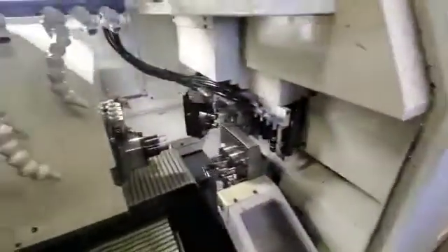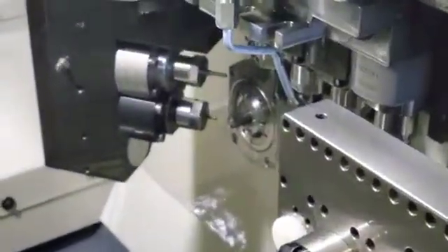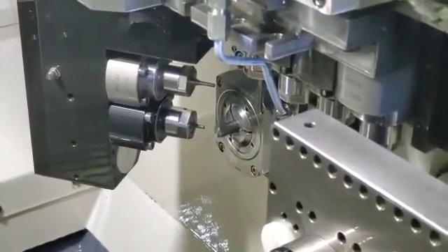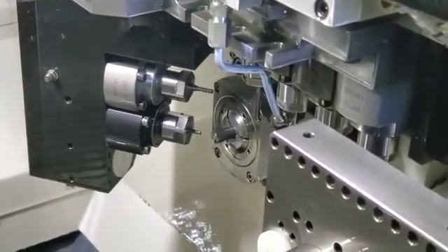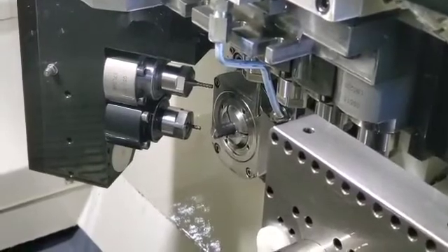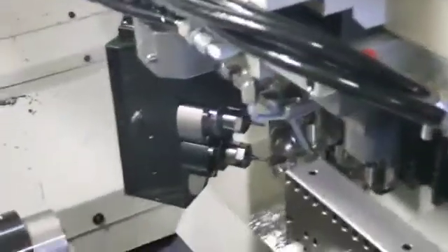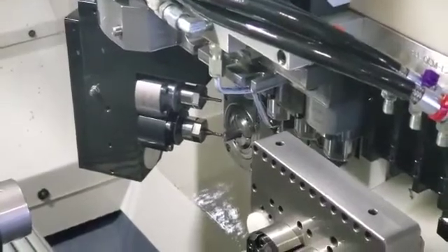So we're going to open up the door and pull that tool out to the corner of the stock. The most critical thing is to make sure that the stock has a sharp corner. If you have a new bar in there, make sure there is no chamfer or anything on that corner. At this point, I pulled that tool out to the corner of the stock. Then we're going to run the next portion. We hit cycle start, and then it pulls it off.